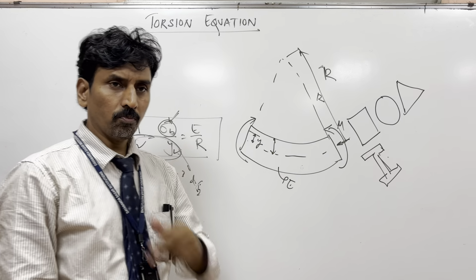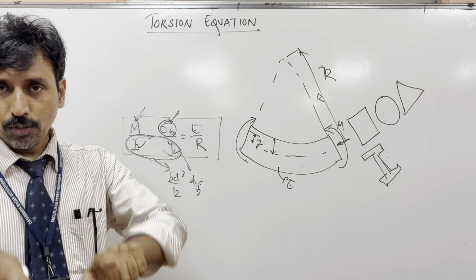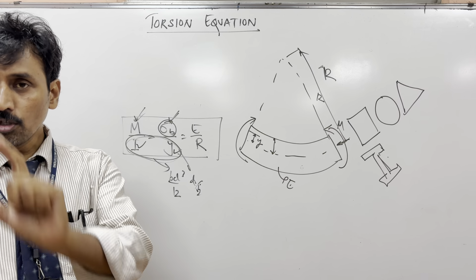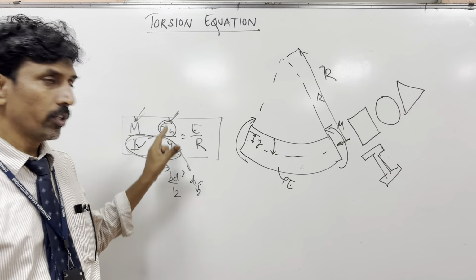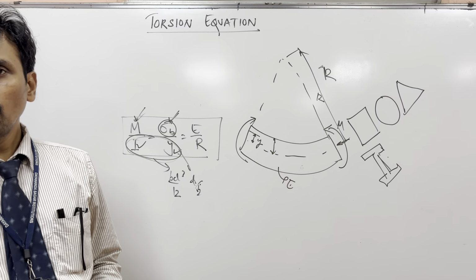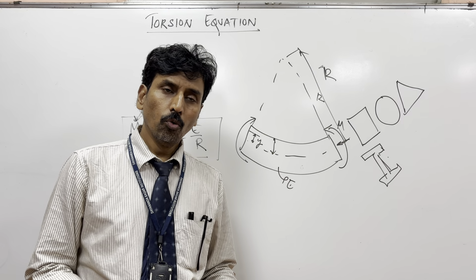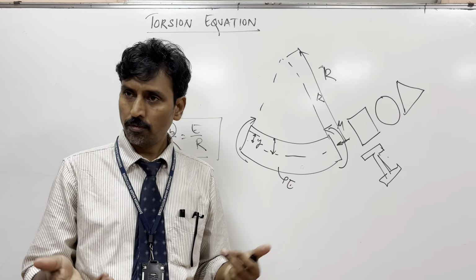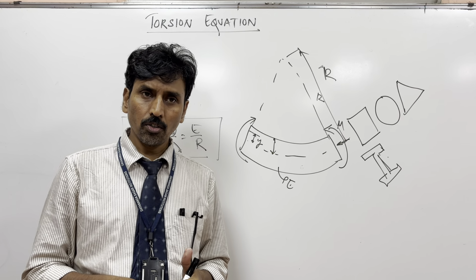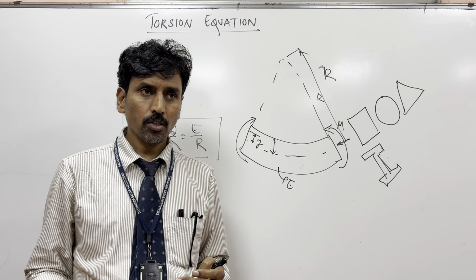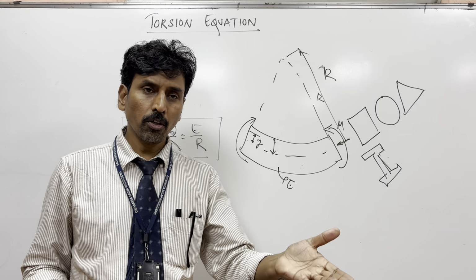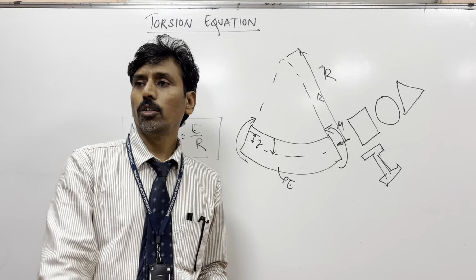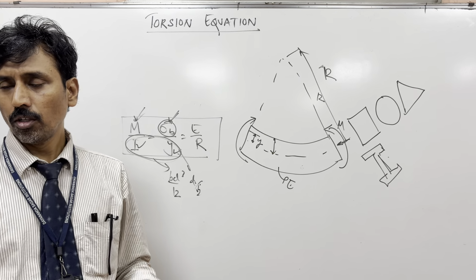So basically for engineers, we come across a lot of components which will have bending forces. If those components should not fail, you should be aware of this equation. Of course, people say you have software like ANSYS which does the analysis for you. But to start with the analysis, you should have some dimension. So you should make some hand calculations approximating a lot of things, because ANSYS doesn't give you the dimension of the component. You should make a component and then feed it to the analysis software with the loads.